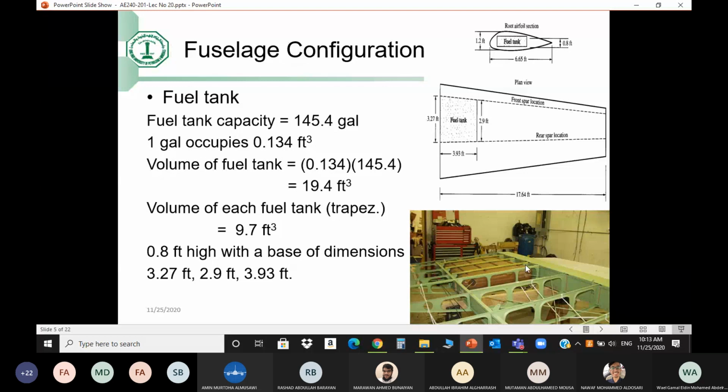In the wing, we have a strong beam that will go from the tip to the root. That's called the spar. And typically we have more than one beam. So we have this as the front spar and this one strong beam as the rear spar. In a top view, that will be the front spar and that will be the rear spar. Typically, the front spar is located at 1/4 of the chord. So you see this line, typically, not always, but close to 1/4 of the chord.